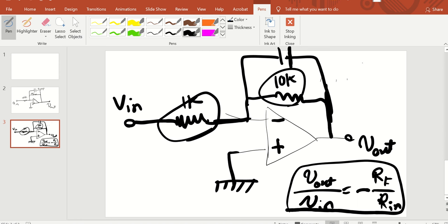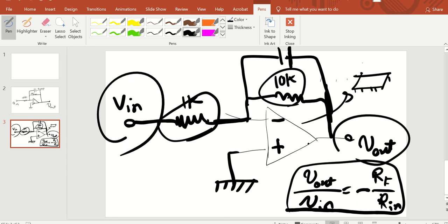So this is a circuit. Let's say I give you this circuit and I ask you to build it with Eagle. The first thing you have to do is look at it and say, okay, I have a resistor, capacitor, and an IC here. And then you need something that you haven't seen before for V out and V in, right? You need some pins for your input and output, so when you have a signal going in, you can see your signal coming out. I'm going to use surface mount for all my components today, okay?